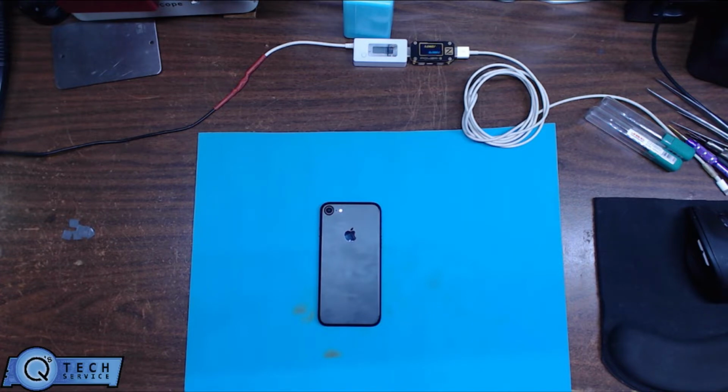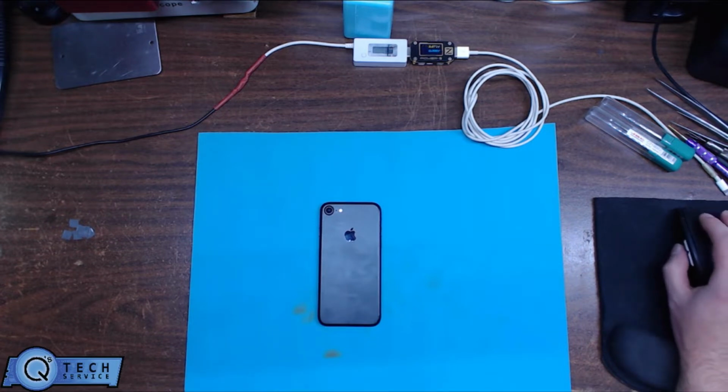So what I'm going to do is pull the audio IC chip up, take it apart, and we're going to run a jumper wire from resistor 1103 to C12. You can run jumpers to the other ones. I'm going to demonstrate here what jumper wires we're going to be running.